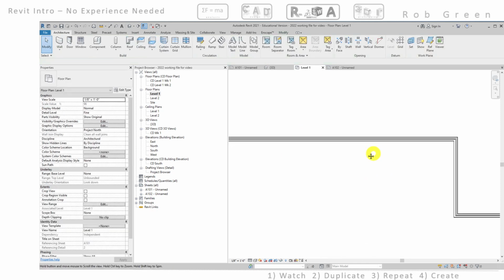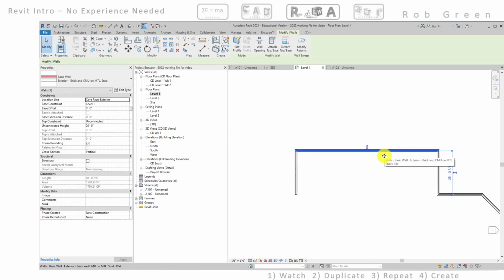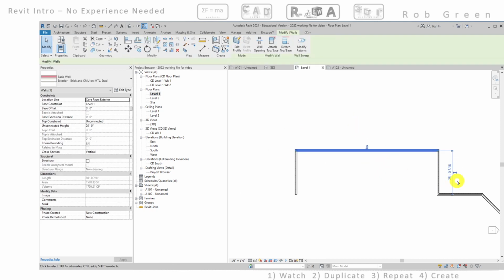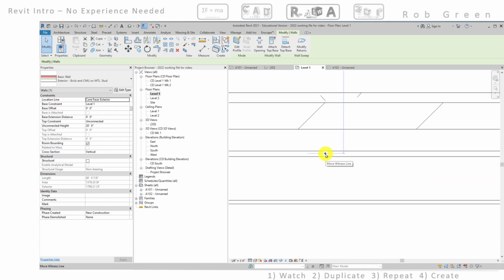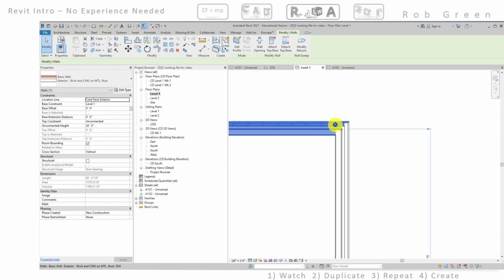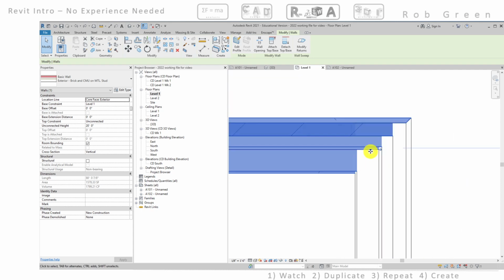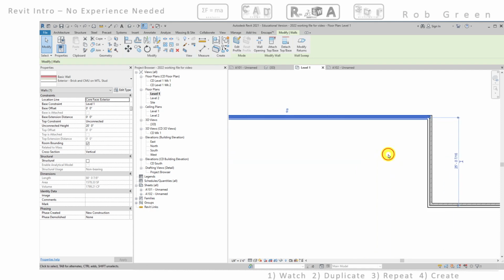Quite frankly, I kind of hope that this isn't 25 feet anymore. In fact, I'm going to drag it down. Whoops, let me Control Z that. Notice if I click this wall out, it says it's 25 feet and 7/16 inches. That's that temporary dimension. That said, if I zoom in, we can see that I'm going from wall center line here to what looks like core face exterior. So yeah, I've got an incorrect dimension. I'm just going to leave it.